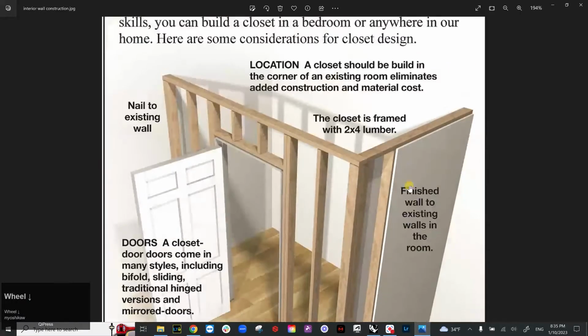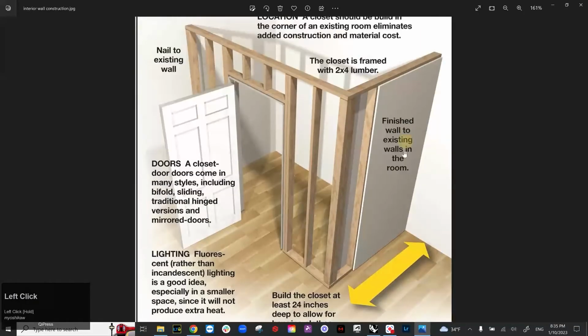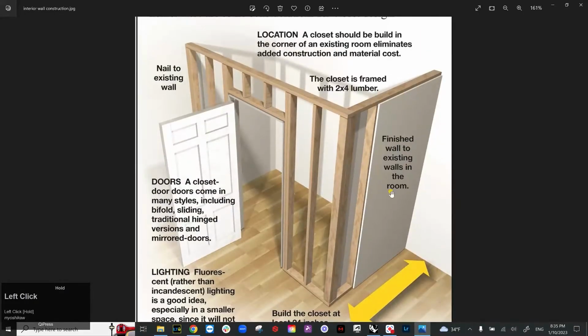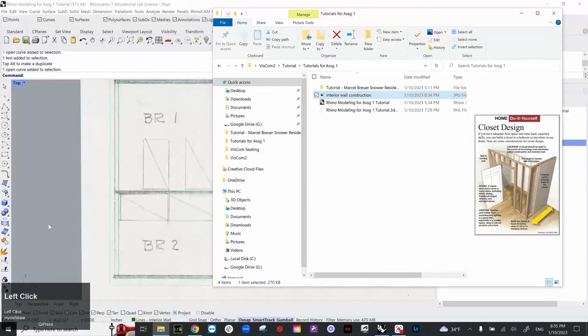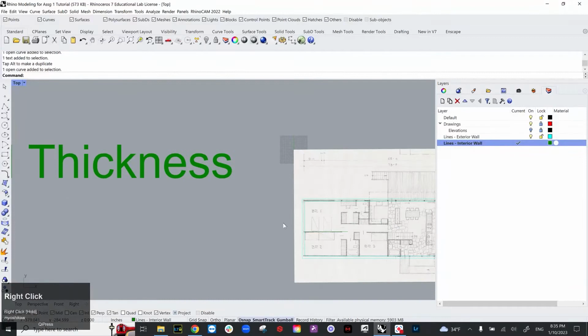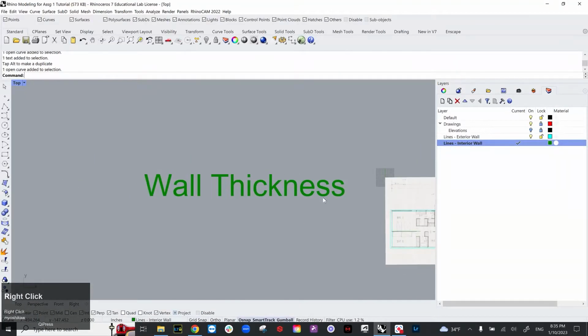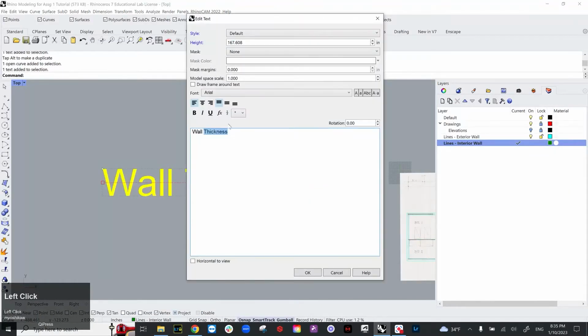This drywall comes in two thicknesses. It comes in 0.5 inches, or it comes in 5/8 inches. We architects and designers always specify 5/8 inches, but then the contractor just changes it to 0.5 inches.